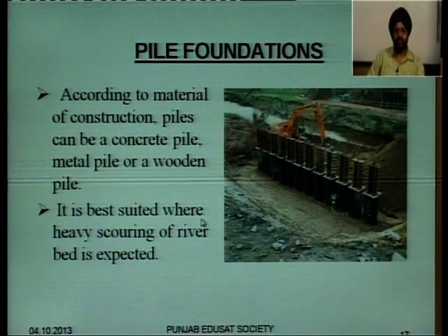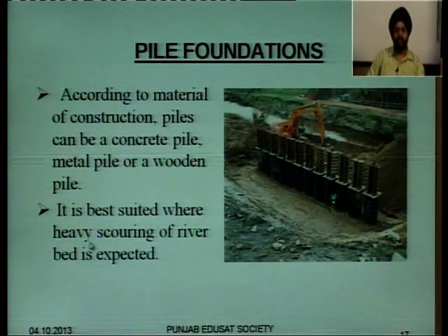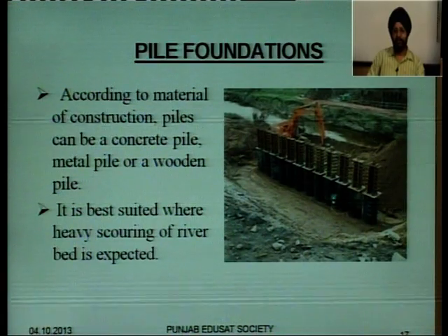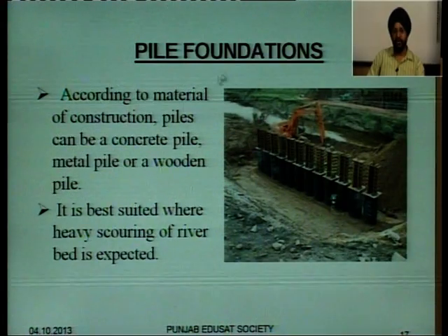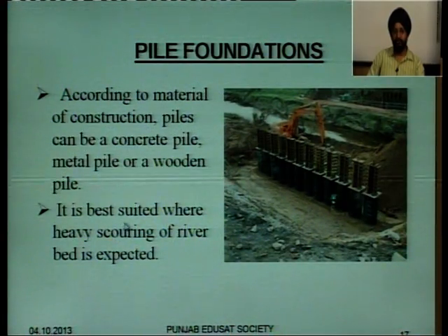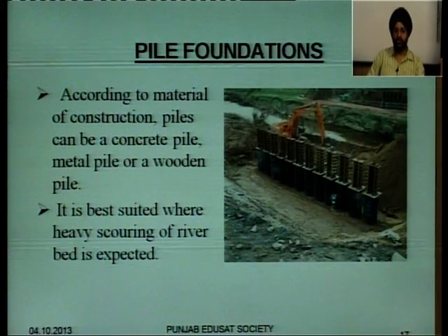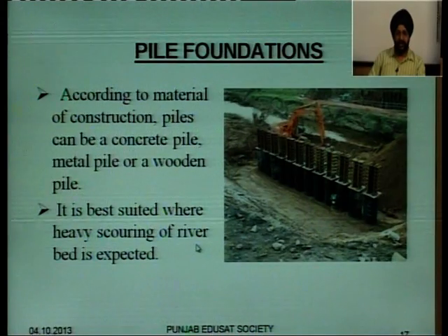Pile foundations are best suited where heavy scouring of river bed is expected. Once again, this is how it is different from spread foundations. I have told you the spread foundations are meant where the scouring is minimum, whereas pile foundations are best suited where heavy scouring of river bed is expected, meaning the river is going to scour or erode in the vertical direction. So this is regarding the general